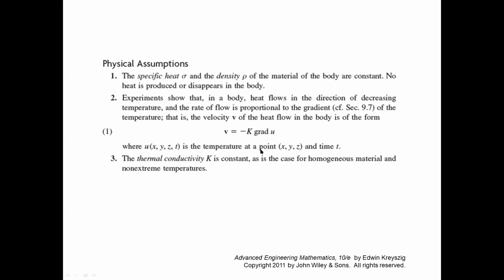Second, this is called Fourier's heat conduction law. The heat flux, that means energy passing through a cross-sectional area per unit time, is proportional to the temperature derivative with respect to distance. And this k is called thermal conductivity.